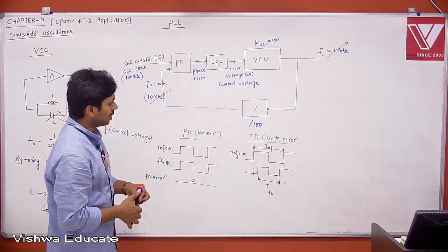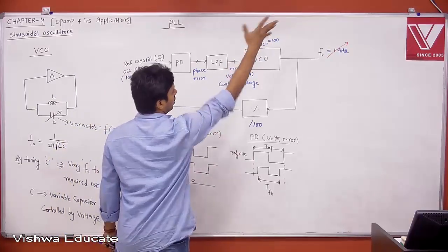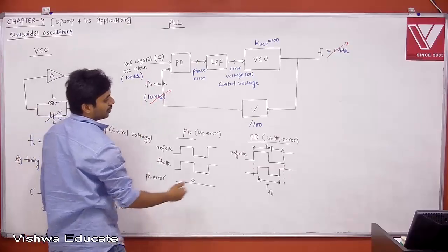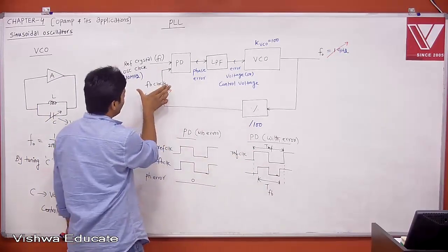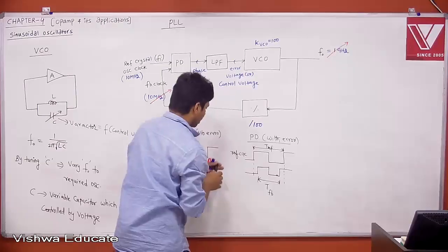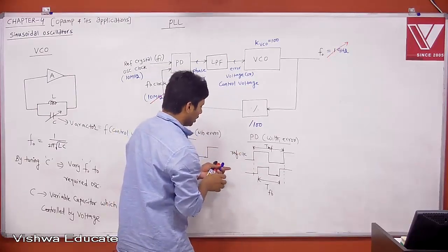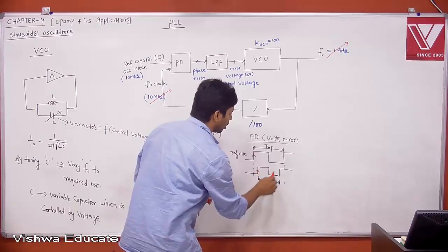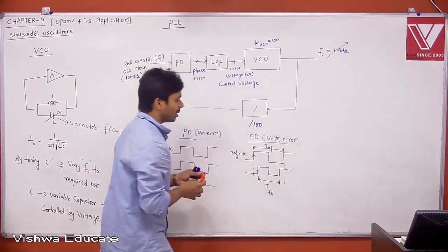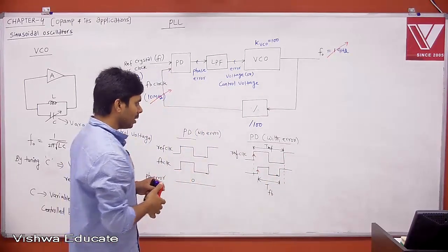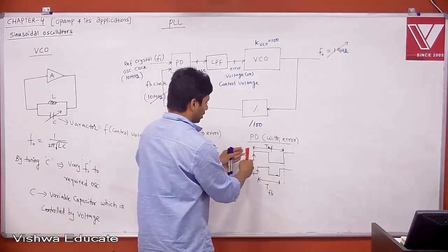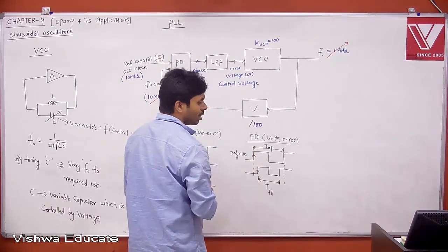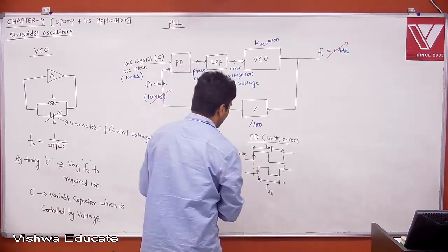Now see, if the frequency is increasing, then it is divided by 100, then it is more than 10 MHz. If it is more than 10 MHz, the period of your feedback clock is decreasing. When the period is decreasing, there is error, right? If you see rising edge to rising edge, this is the ideal clock, and this is your other clock. The rising edge of this has some variation. Then tell me what we get at the output. You will get some variation.